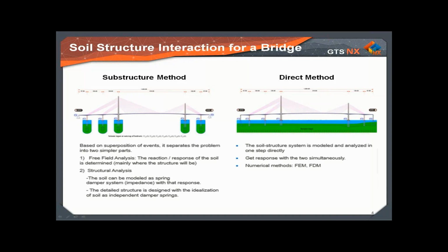In the second step, the structure supported by this spring damper system is analyzed by a load case that depends on the free field movement. That stage corresponds to inertial interaction, hence the mass of the structure and foundation is considered.